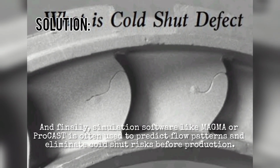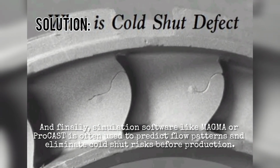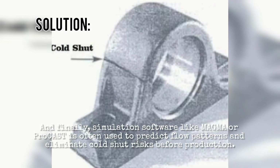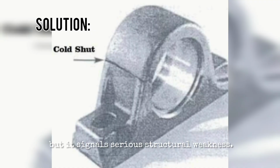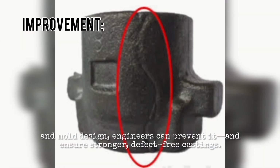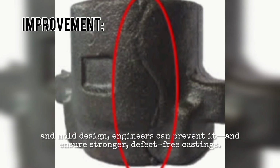And finally, simulation software like Magma or ProCAST is often used to predict flow patterns and eliminate cold shut risks before production. A cold shut may look like a simple surface defect, but it signals serious structural weakness. By controlling temperature, flow, and mold design, engineers can prevent it and ensure stronger, defect-free castings.